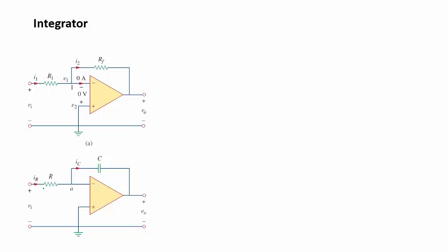So using Kirchhoff's current law and applying our rules of op-amps, we have that the current going into node A equals the current going out of node A. So I through the resistor equals I through the capacitor leg of this circuit. Current in equals current out, which is a direct application of KCL using our op-amp rules assumption. So we can get I in the resistor, that's the input voltage V1 minus VA over R. And we can also get the current in the capacitor, which is